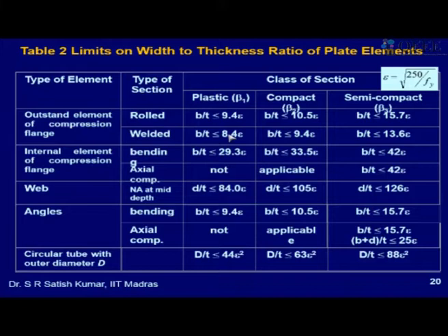Basically, what happens is when you weld a section, you create much more residual stresses. So as a consequence, the plate buckling gets affected. Like yesterday we saw columns which have welded sections have a lower strength curve compared to rolled sections. So basically that is residual stresses, and there may be what is called weld distortion sometimes. So that has also been included into these numbers.